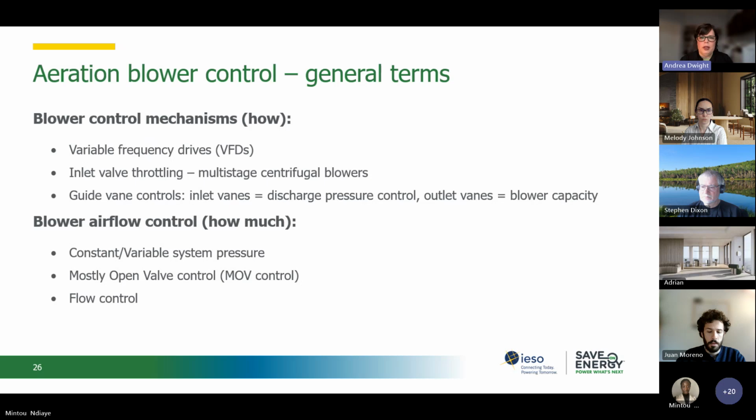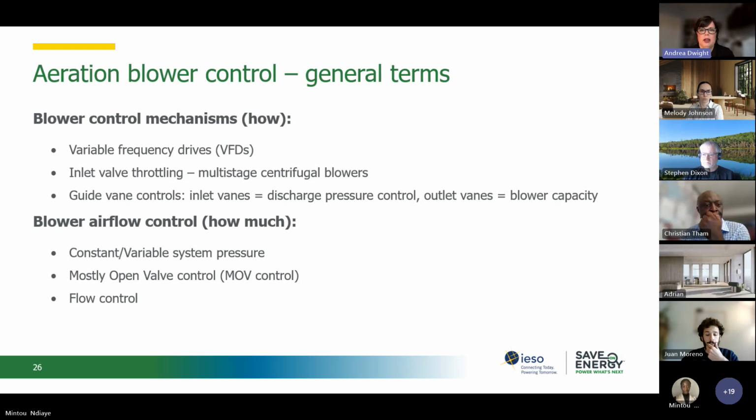So in general, just so we're all on the same page, most blowers are physically controlled through variable frequency drives or through inlet vane throttling or guide vanes. And obviously, controlling your motor speed is the most energy efficient method. So you need to try and move to that if you're not doing it now.